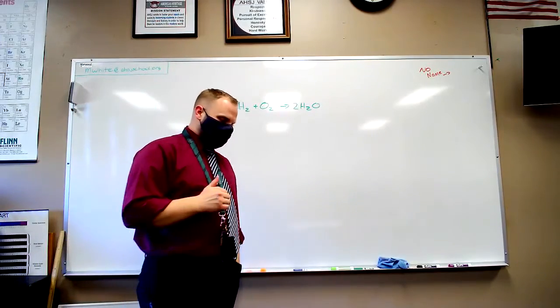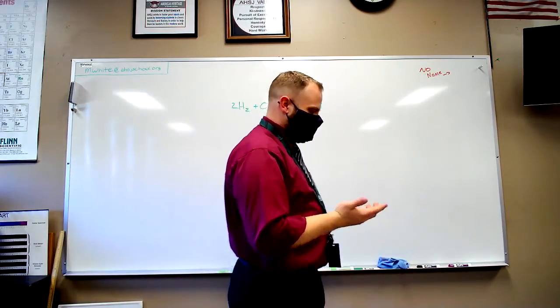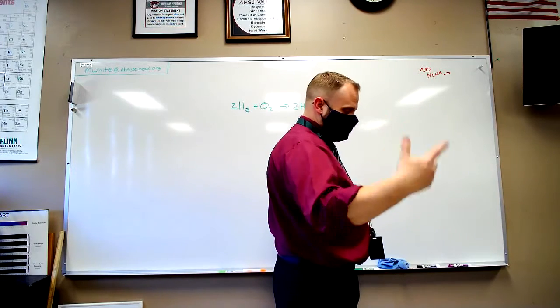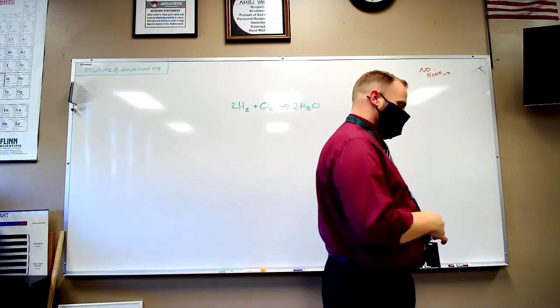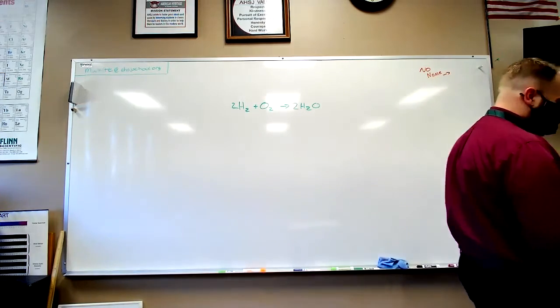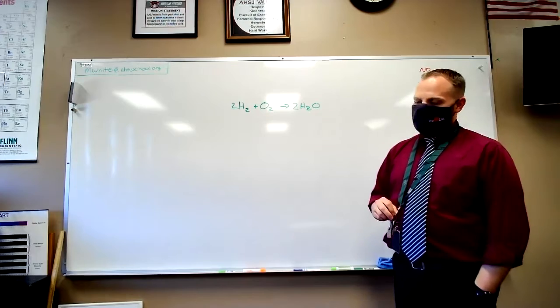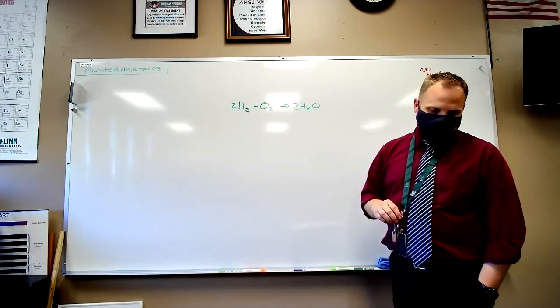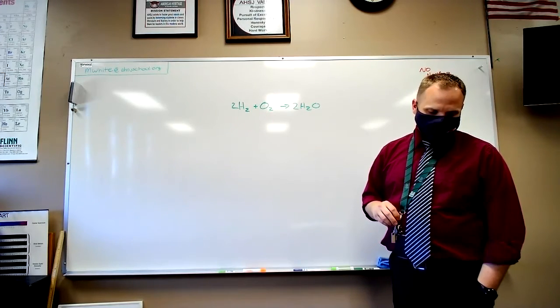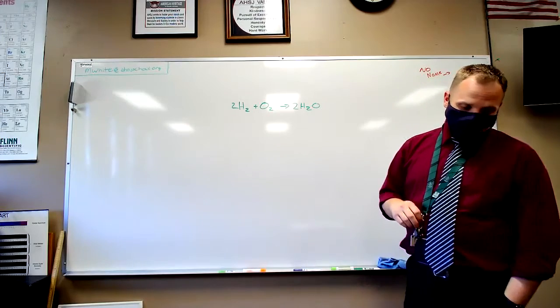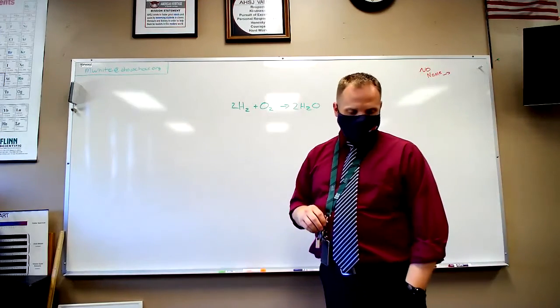Now, if you are paying attention, you can replace these sacrificial pieces and extend the life. If you're not, once they get used up, then the steel tank starts to erode away, and eventually your water heater fails.